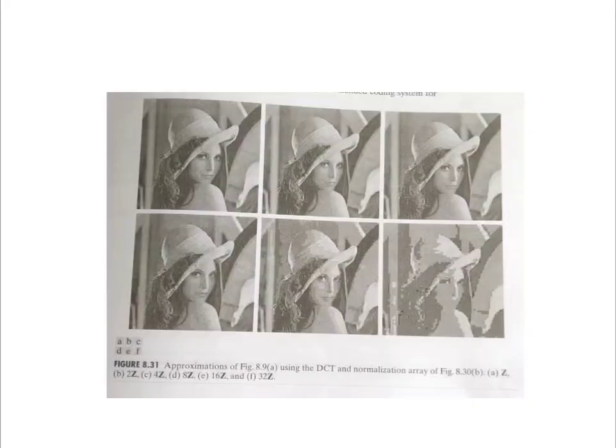The remaining results, which compressed the original image by 19, 30, 49, 85 and 182 to 1, were generated after multiplying the normalization array by 2, 4, 8, 16 and 32 respectively. The corresponding RMS errors are 3.83, 4.93, 6.62, 9.35, 13.94 and 22.46 intensity levels.